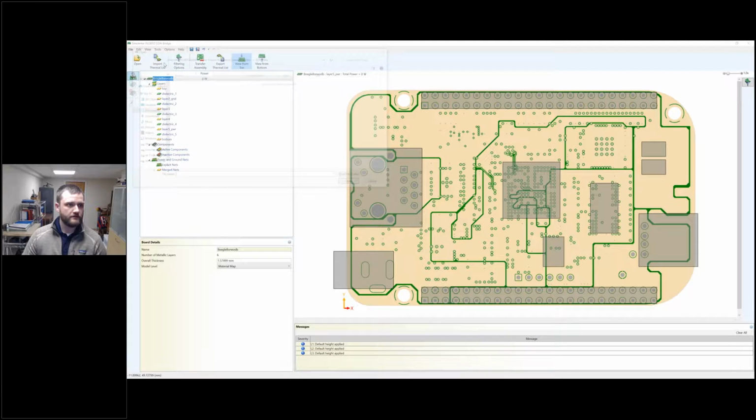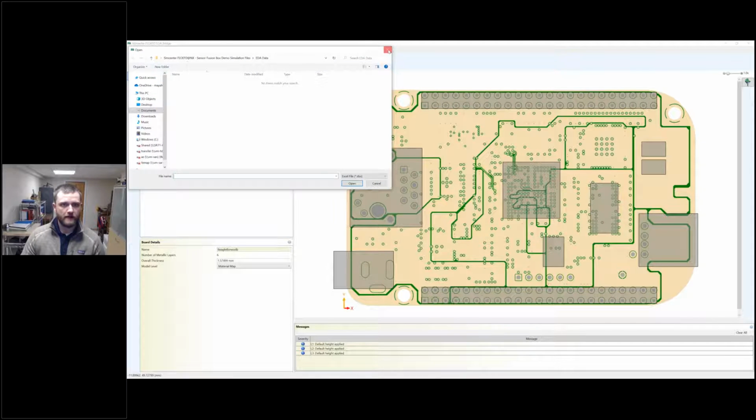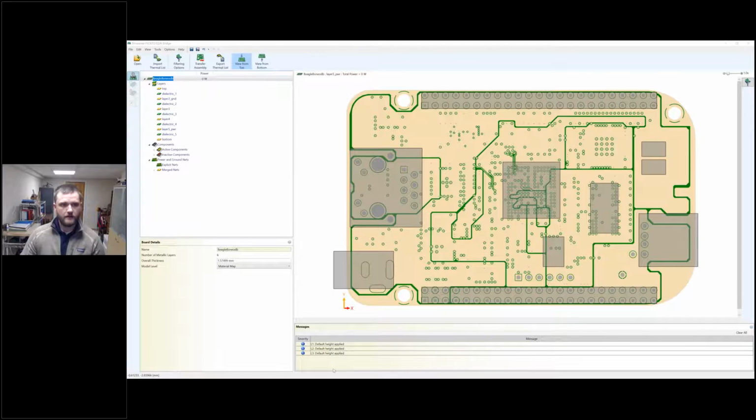So we'll just go ahead and do an import of a thermal list. But before I do that, I'll actually show you the thermal list. With a thermal list, we're able to basically assign power, and these are used as a reference designator that are also tied to CAD, the model type, and whether or not they'll be filtered out. We also can look at the max T junction, the maximum case junction for the ICs, also the resistance of the components, and then finally the power for each one.